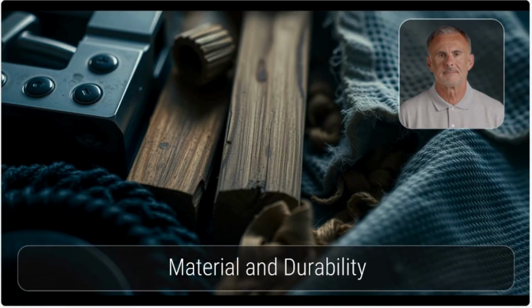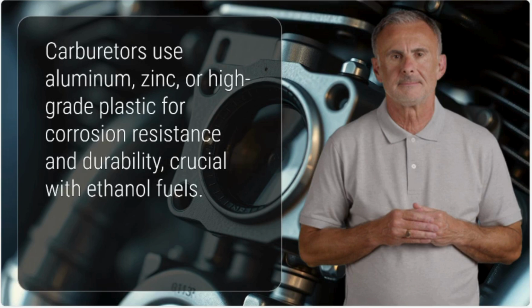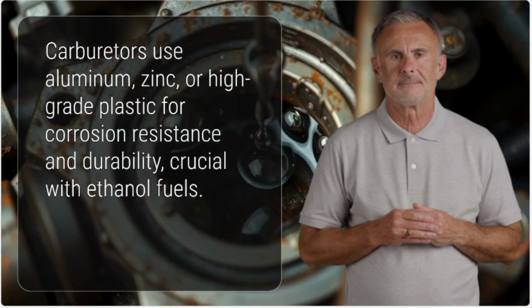Material and durability. Carburetors are typically made from aluminum, zinc, or high-grade plastic, all chosen for their corrosion resistance and durability. These materials are important, especially with the increasing use of ethanol-blended fuels, which can attract moisture and degrade internal parts if not properly stabilized.